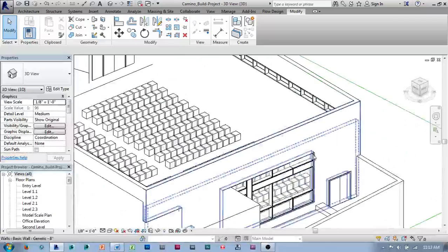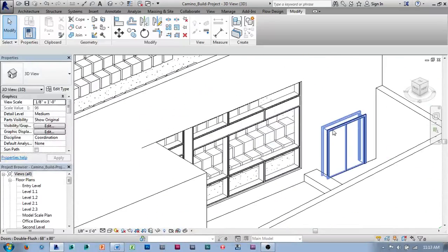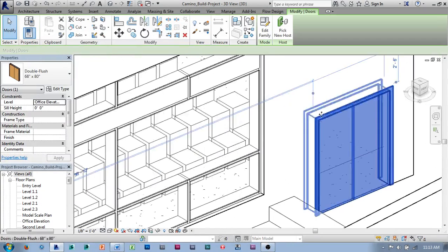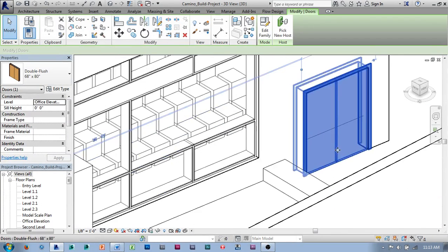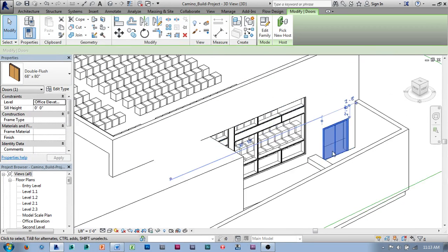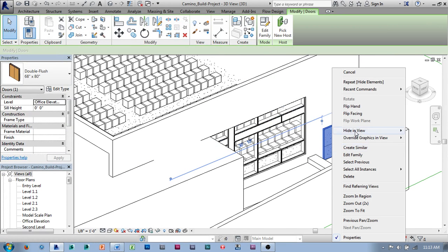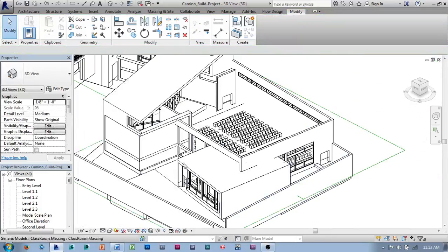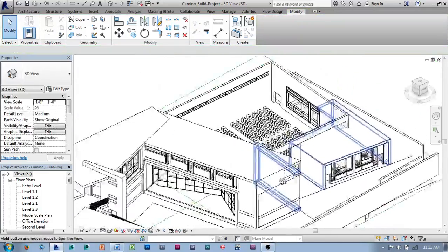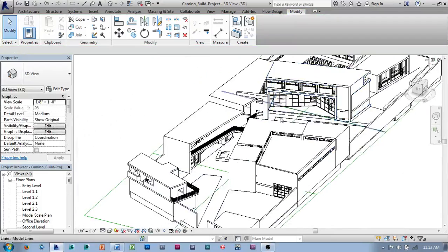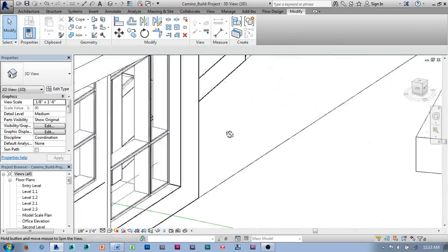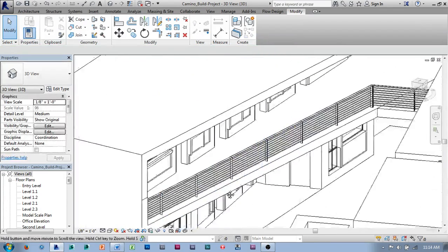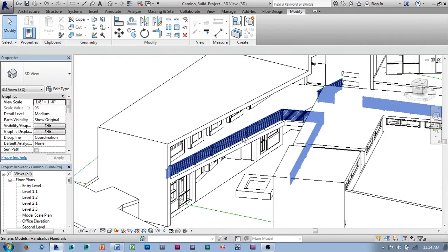The last thing that I do want to do is things like doors. The door frame, again, is going to be too small of a detail, and the door itself, a lot of times those are too thin. They're not going to print very well either. So hopefully I can just do those as an entire category and get rid of the doors pretty much everywhere in one click. And it looks like that's worked pretty well. Oh, last thing too, handrails. Definitely not going to print those, but we do want to replace those with something that's more like a solid wall.